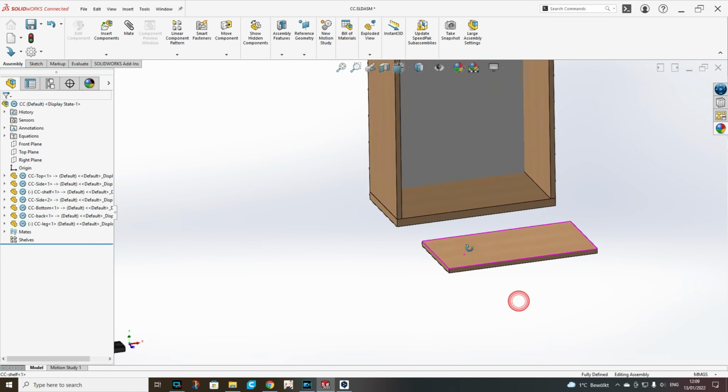So first we put these equations, then when you double click on the distance you will have the size. Once you have the size, you can choose the global variable which is controlling it. It's the same with features. That's why we were first making the boss extrude and then changing the size. Now it will be controlled from this global variable. Again, we save everything.